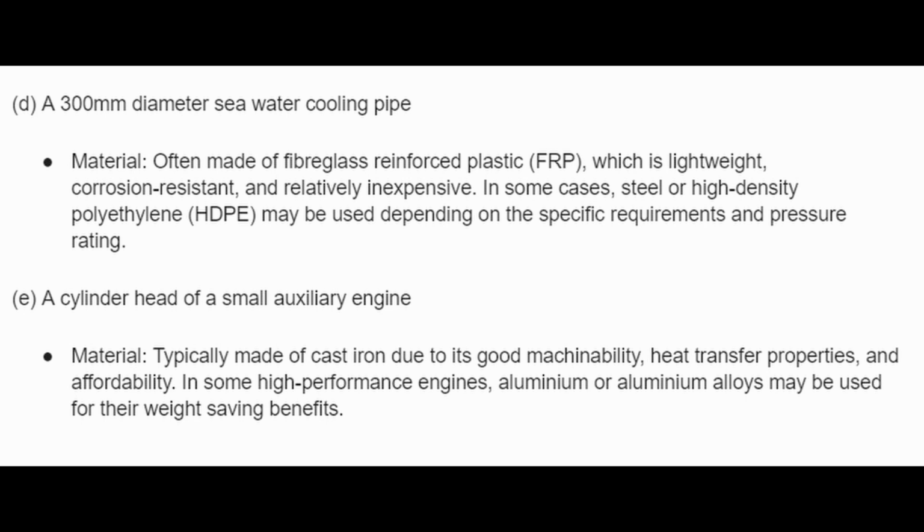E. A cylinder head of a small auxiliary engine. Material: typically made of cast iron due to its good machinability, heat transfer properties, and affordability. In some high-performance engines, aluminium or aluminium alloys may be used for their weight-saving benefits.